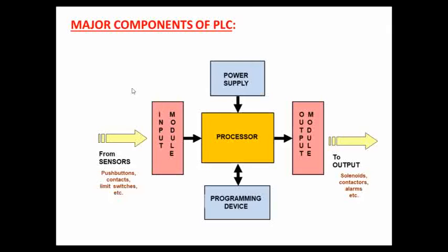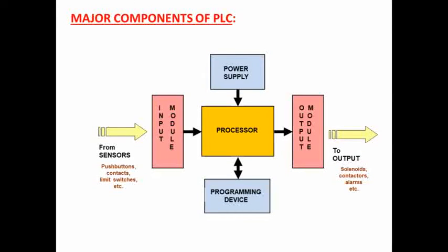What is the executive memory? It is the collection of the permanently stored programs that are considered part of the PLC itself. These supervisory programs direct all the system activities such as execution of the control program and communication with the peripheral devices. The application memory basically provides the need for storing the data area for user program instructions that form the application program. The application memory area is composed of several areas, each having a specific function and usage.